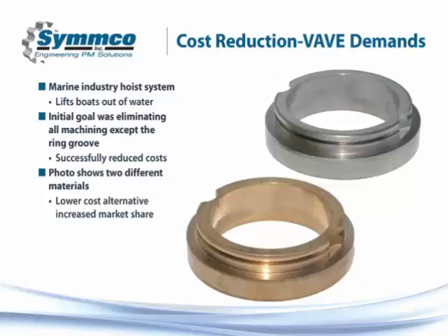What we were able to do is take a look at their margin and create these very large pieces as compact, sintered, and pressed, minus that groove for the ring. So we removed totally all of the machining except that ring groove and saved a lot of scrap in doing so.